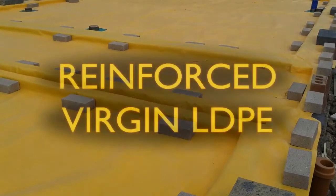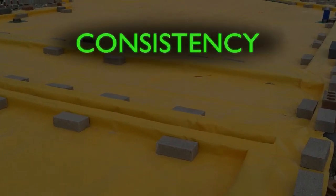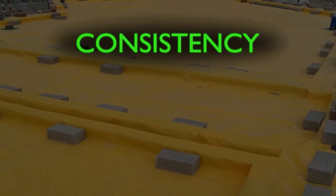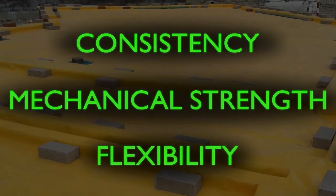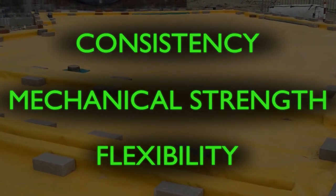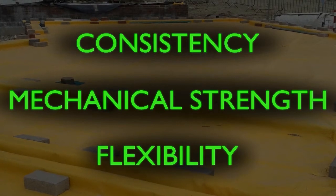Reinforced virgin LDPEs. Reinforced membranes made from a high-quality virgin LDPE are inherently more consistent, as good control of thickness and material tolerance is critical for achieving a good lamination with reinforcement. This reinforcement also greatly improves the membrane's resistance to tearing and damage while allowing the membrane to retain its flexibility. This results in a good balance of durability, performance, ease of installation and cost. It is, however, important when using these membranes to have a good understanding of the risks present on site to ensure the vapour or gas permeability of the membrane is adequate for the application.